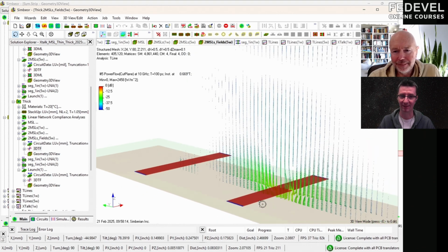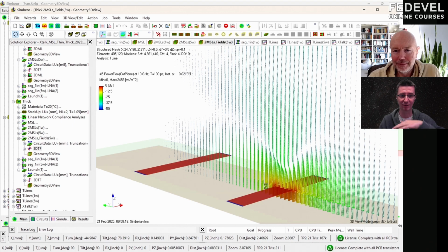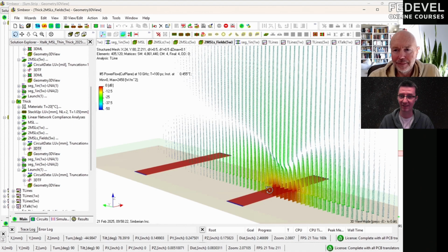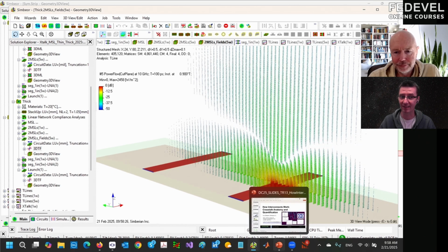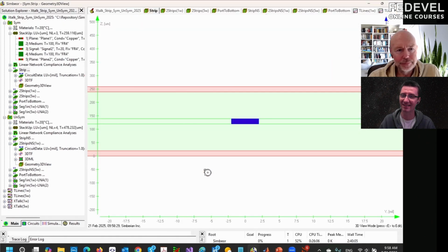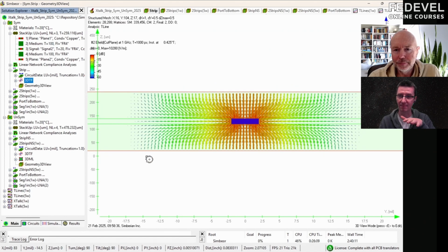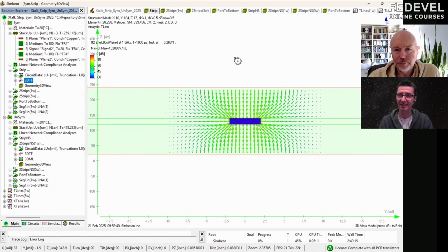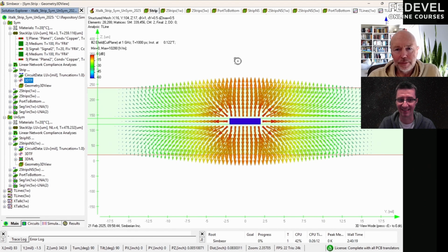So first, what I was very curious to know is the difference between routing on the top and bottom layer, or having the tracks on top and bottom layer, compared to if they are inside of the PCB. So we have two more basic examples. Basically, when the track is routed symmetrically between two ground planes, or when it is asymmetric. So what is the difference?